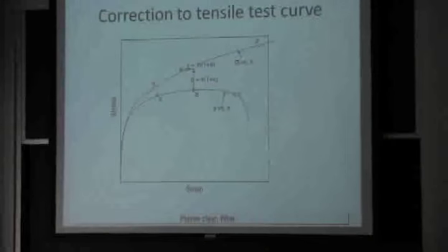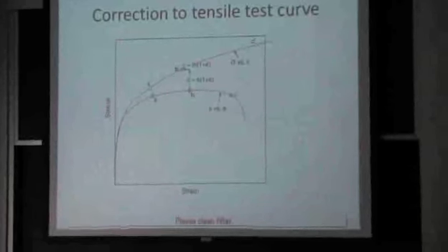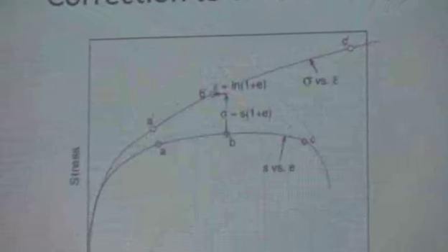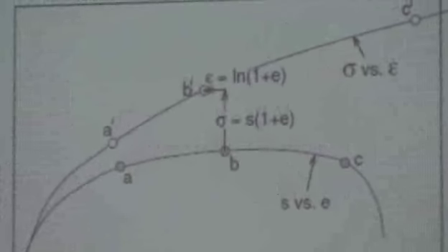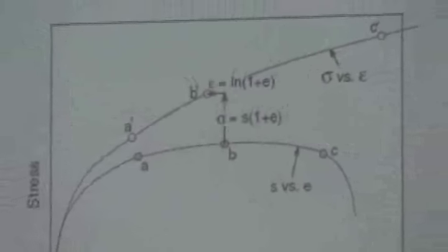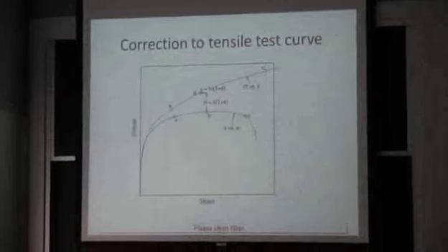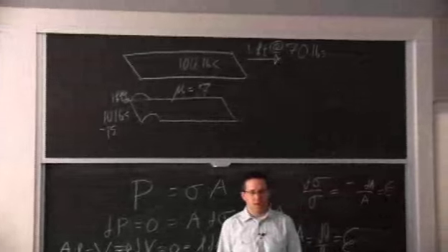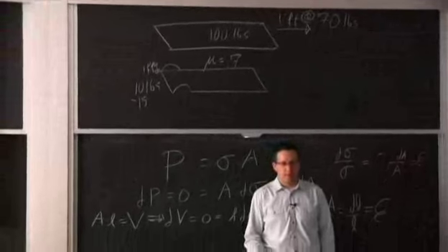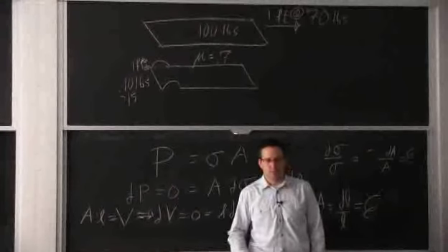And that should make you think that it really doesn't relate to fracture. I mean, does it? If the peak of the stress strain curve is the strain hardening exponent value in terms of strain, it's really a property related to work hardening of my sample as opposed to being related to a fracture resistance.